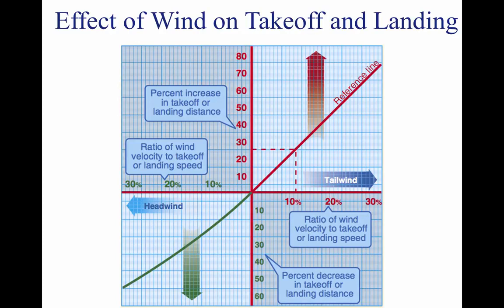Landing performance. In many cases, the landing distance of an aircraft will define the runway requirements for flight operations. The minimum landing distance is obtained by landing at some minimum safe speed, which allows sufficient margin above stall and provides satisfactory control and capability for a go-around.